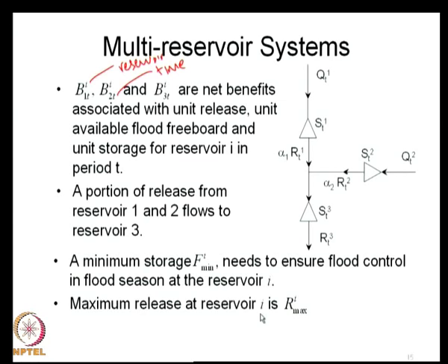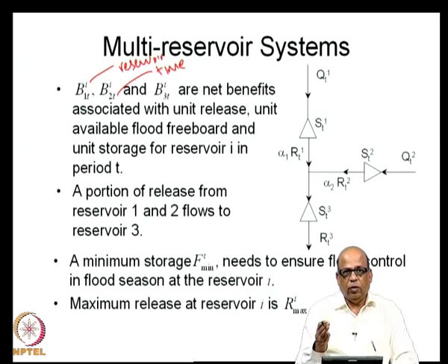So, you have the flood control requirement, you have the maximum release requirement, and you have the benefits associated with the release from a reservoir, the storage available in the reservoir, as well as the flood freeboard that you keep in the reservoir. Now, this is the typical problem which we will formulate as an optimization problem now.